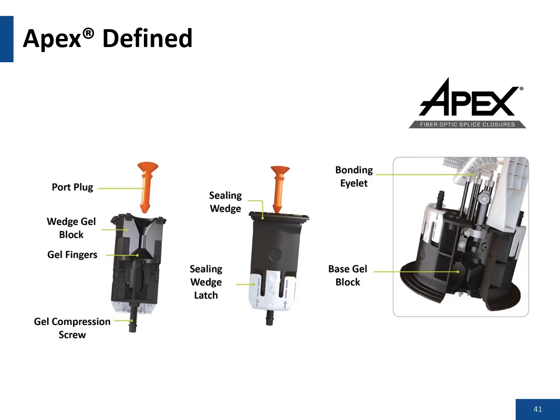Again, closures typically will have either a gel entry system or they'll have a grommeting system or grommeting technology on the new generation closures out there today, where the old styles were using heat shrinks and rubber mastic tapes and washer-based systems. The newer closures that are using gel entry are very fast, with very few piece parts to assemble, and typically the ports are independent of each other.